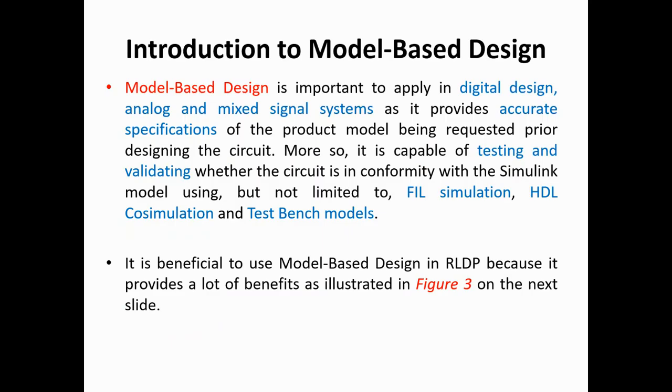Model-based design is an important tool to apply in digital design, analog, and mixed signal systems because it provides accurate specifications of the product model being requested prior to designing the circuit. So it is capable of testing and validating whether the circuit is in conformity with a Simulink model using, but not limited to, FIL simulation, HDL co-simulation, and test bench models.